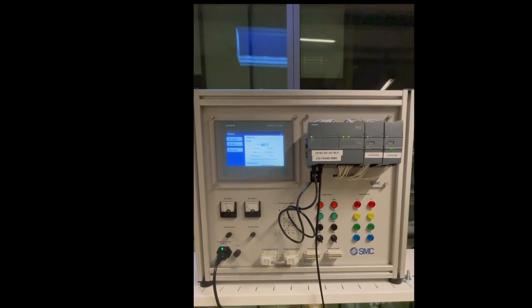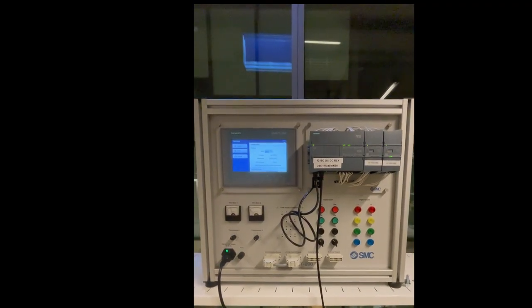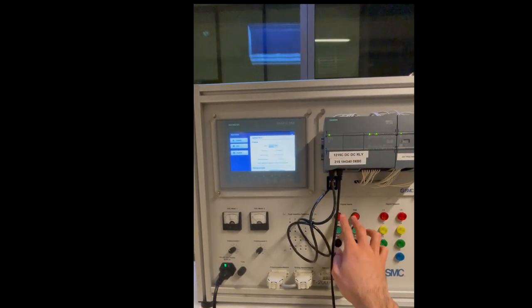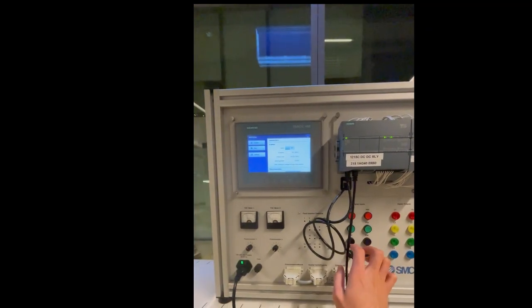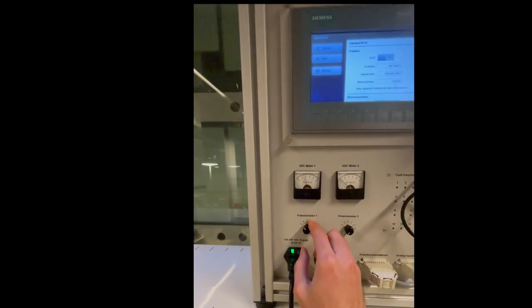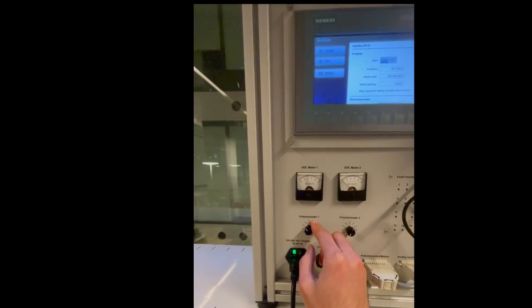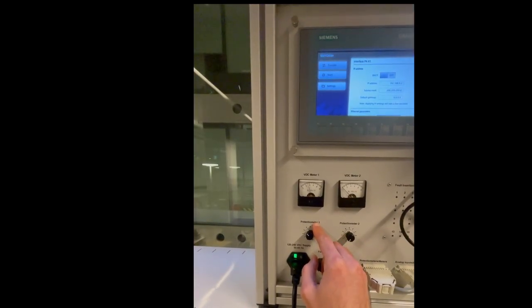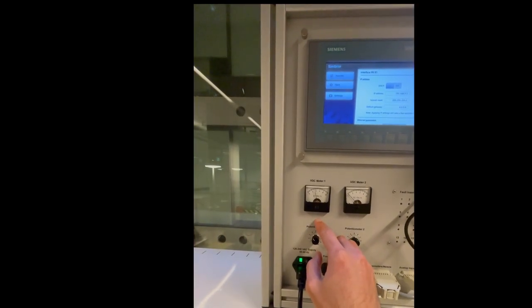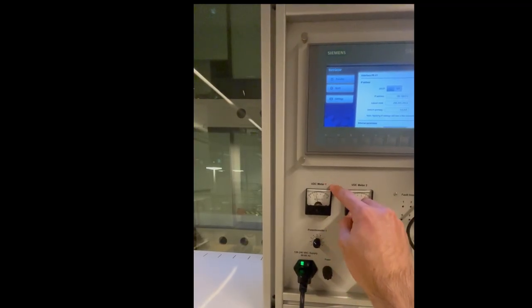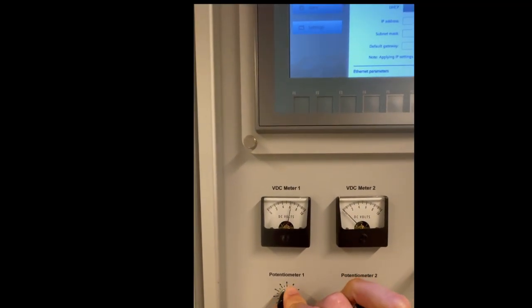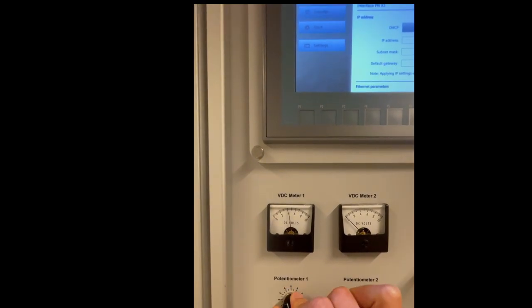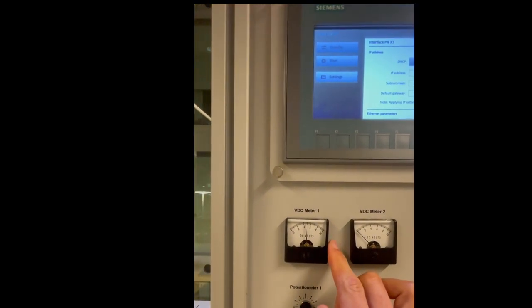Alrighty, so just as a checkpoint, guys, so far we have programmed these 4 buttons to turn on LEDs. These have not been coded. We programmed the analog input connected to this potentiometer. We are reading this measurement and then using the measurement to command the analog output, which is connected to the voltmeter 1. And as you can see here now, if we change this value, we'll change the voltage for the input and consequently the voltage for the output.